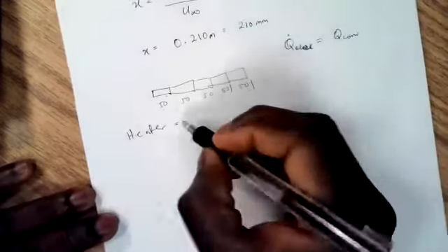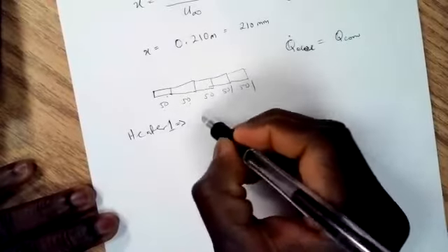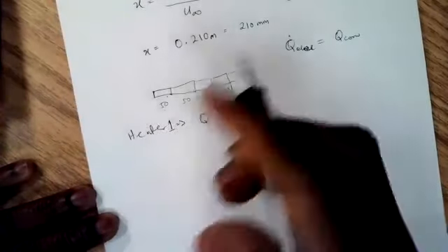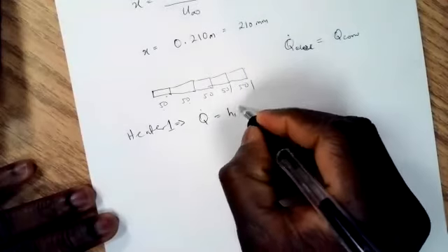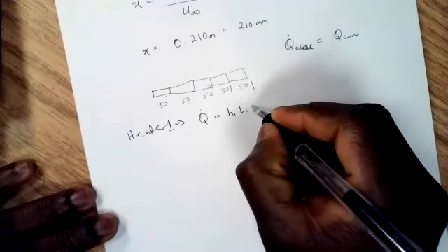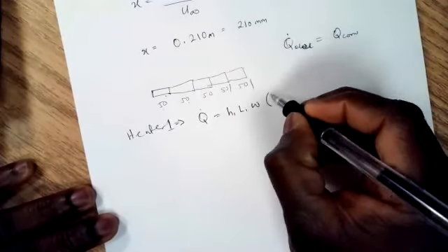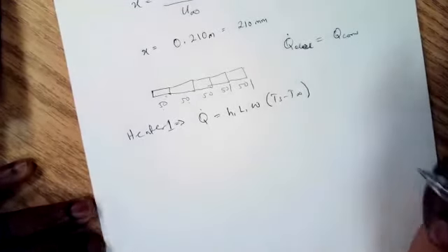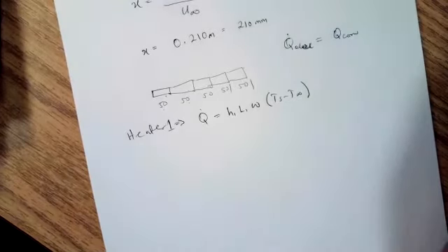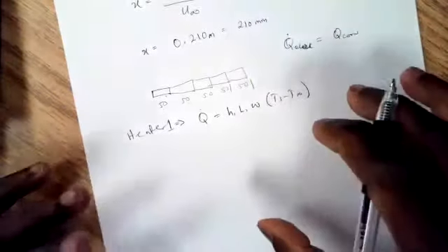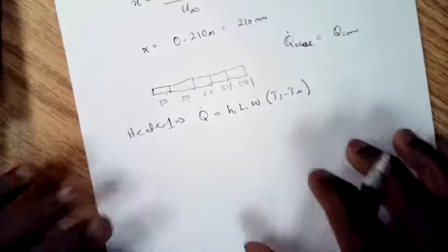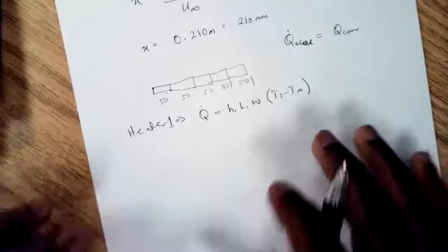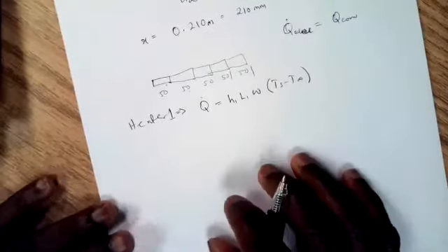So now for heater 1, let's compute Q dot. This is h1 L1 multiplied by Ts minus T infinity, to find the amount of heat convected away. Now we have to find what kind of system we have at that point, now that we have sufficient information.